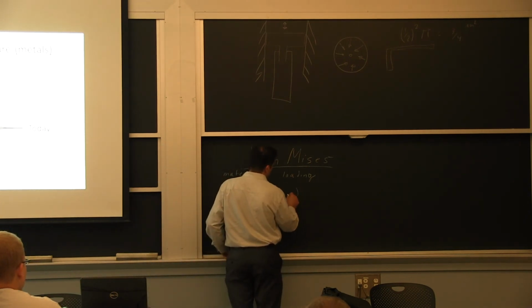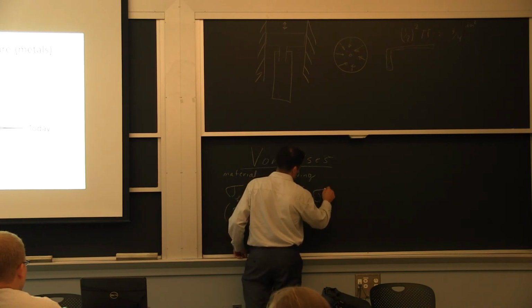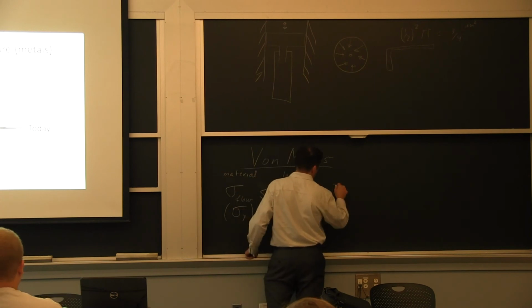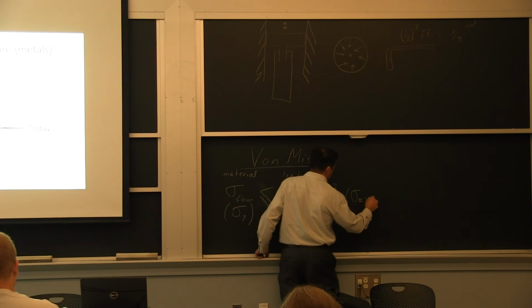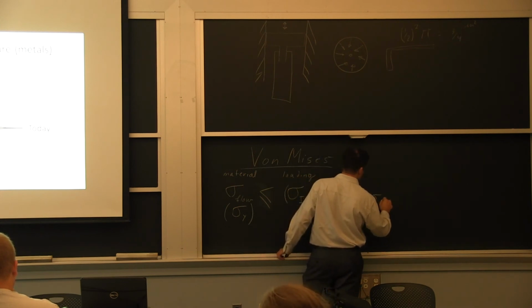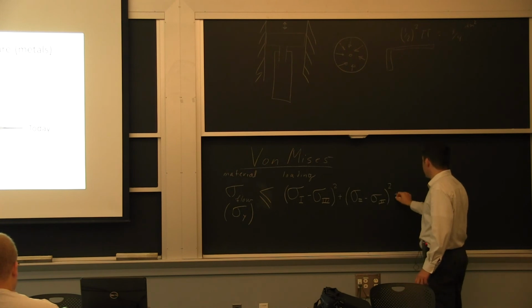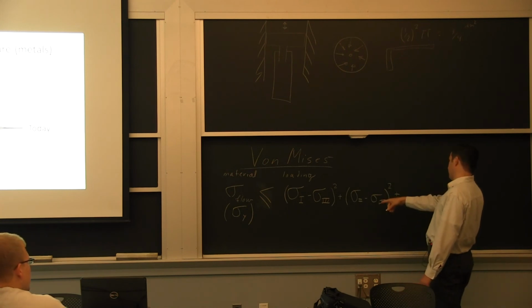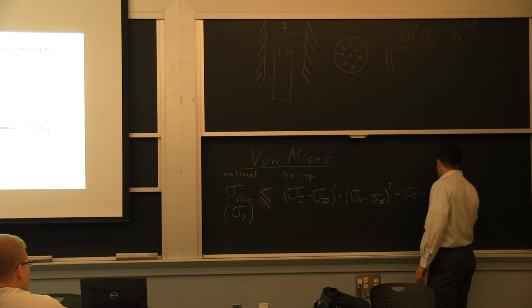And then it's really a deviatoric stress, if you remember. So I can write it any way I want here, as long as I make differences between the three principal stresses. So I'm putting numbers in Roman format here. This is all in the principal stress system.